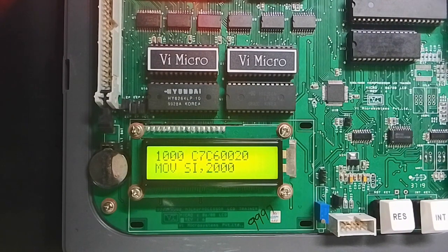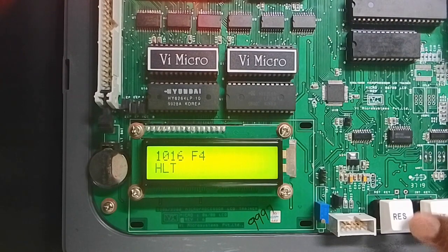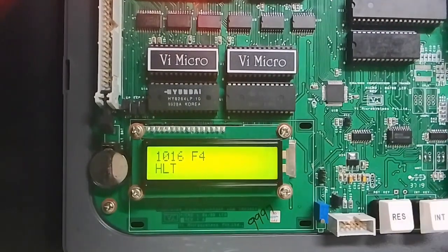First element I am putting in the first array, 2000, second array, 2010. After that CX is 05, AL moving with the address. This is the address which I have to calculate, keep it ready, 100C. Addition of those elements, and after that moving the value of AL to SI, and after that increment SI, after that increment DI, and after that I give the memory location 100C there. So halt. Then I can press my reset.